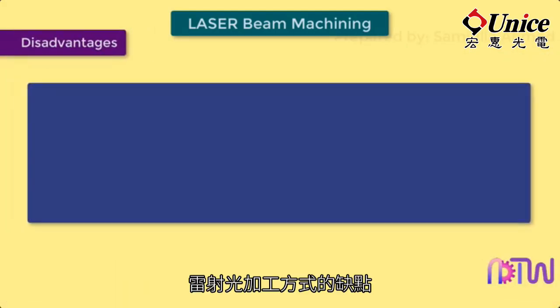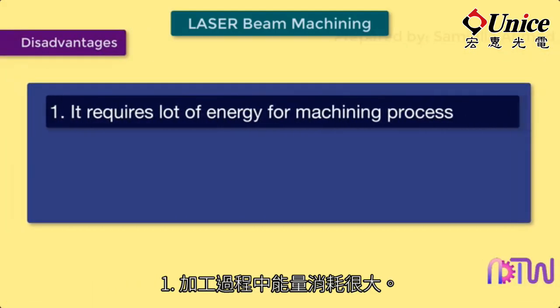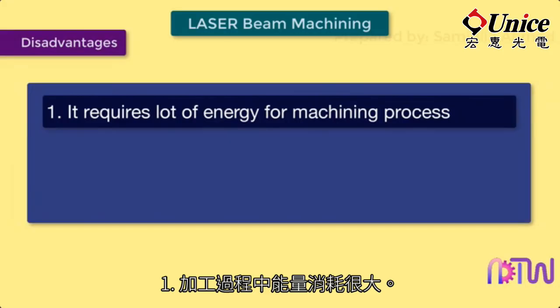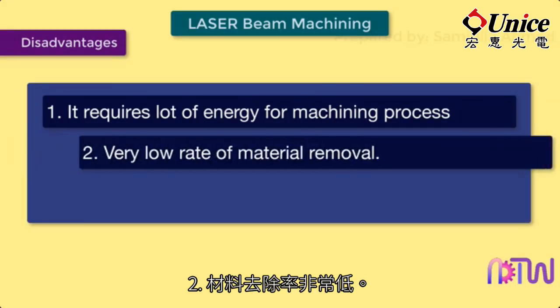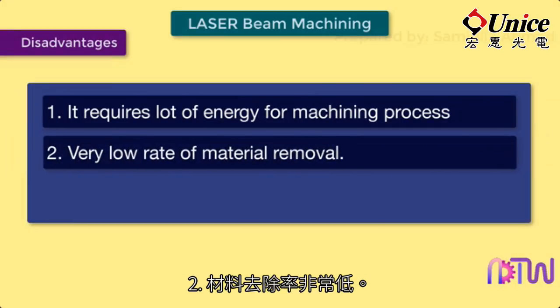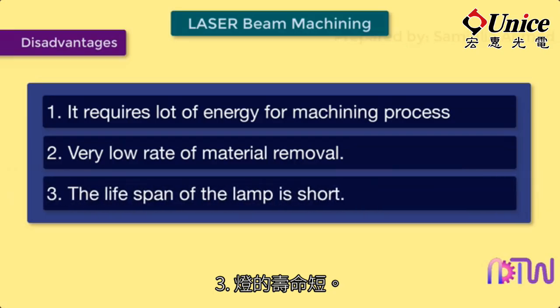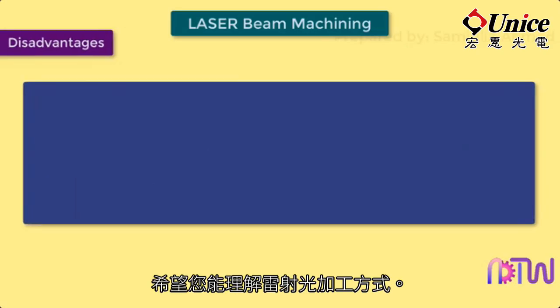Disadvantages of laser beam machining. 1. It requires a lot of energy for the machining process. 2. Very low rate of material removal. 3. The lifespan of the lamp is short. Hope you have understood the laser beam machining process.